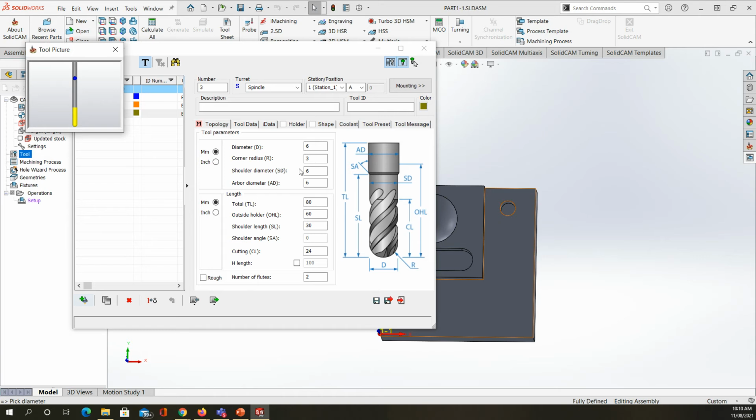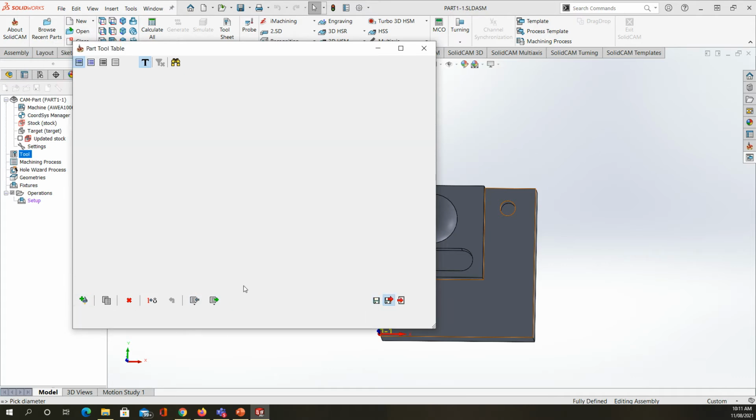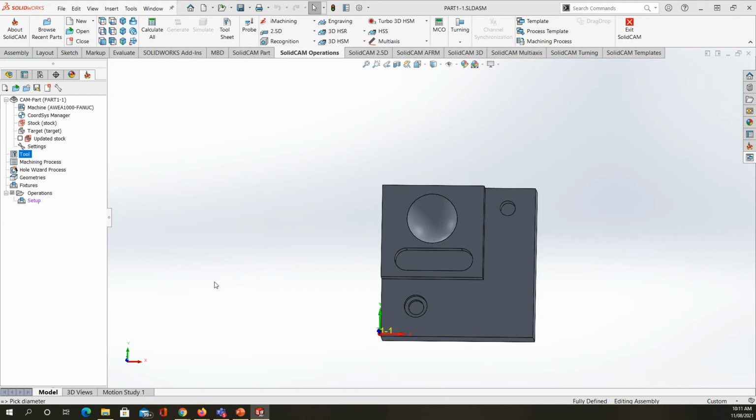And I'm going to make it 5 millimeters. This will be fair and good to give me a good surface finishing. And just remember that the cutting is going to be from this side and the center, not like the flat head for the face milling, which cuts only from the face and the vertical side. This one is going to do it on the whole radius of the cutting tool to shape the spherical shapes. So we have this cutting tool ready, save and exit, done. We define the 3 cutting tools.